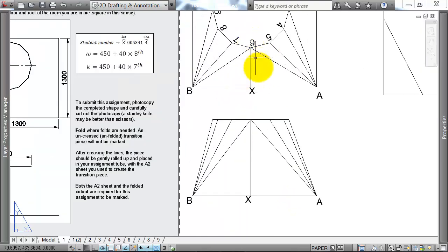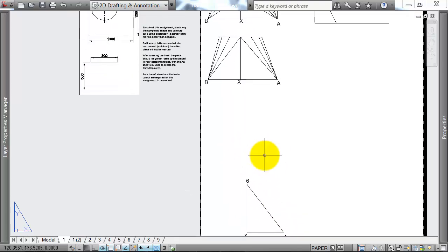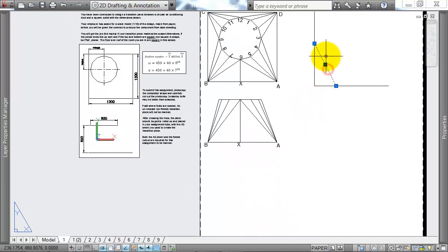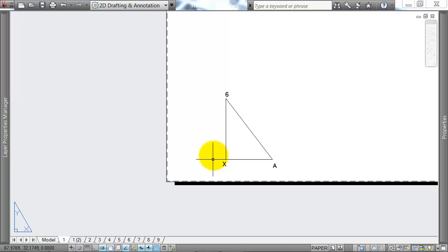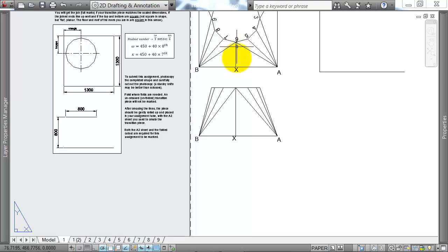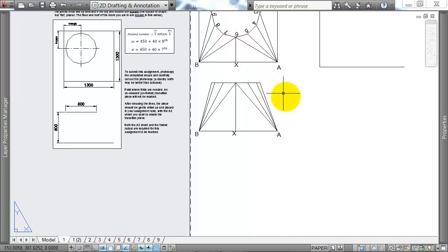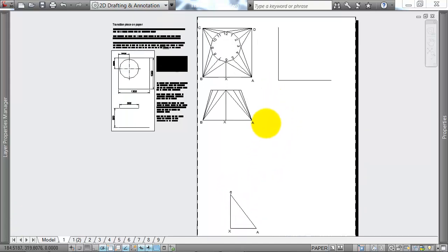Right, so now I've got the first part of that there. From triangle x6a, I can now use what I've already got on the drawing board to find the value of line a6. Now you might wonder, how is it that we know that that's the true value? Well, if I know that xa and x6 are at right angles to each other, as they would be in the true shape of this value, in plane with the triangle BA6, we're talking about a right angle at 6xa, then I can just draw a line straight between these 2 points, having already found both of their lengths, and I find the length of line A6.